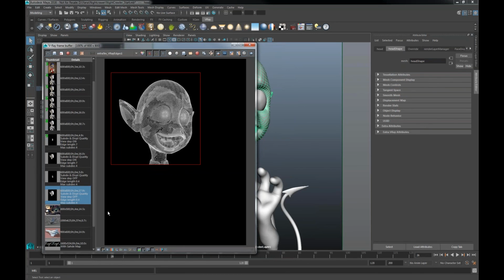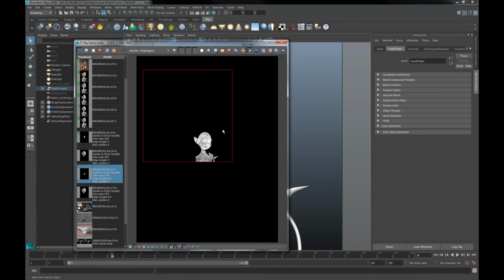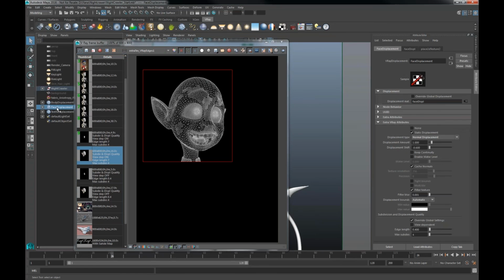But when the object is away from the camera, V-Ray will still subdivide the mesh, because again, the length of the edge will be measured, and since this is in scene units, V-Ray will subdivide it again. And this is why I usually use the V-Ray displacement with view dependent enabled. When this is enabled, this will be considered in pixels. So this example I have rendered with 7 pixels and view dependent on. So this is the result what I get. So if this time the edge length is longer than 4 pixels, V-Ray will subdivide it.